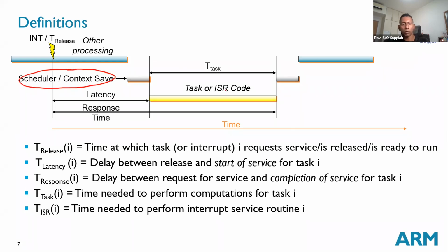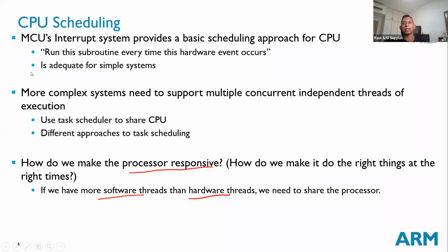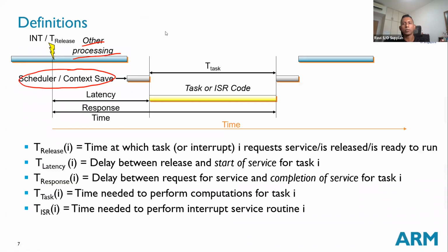If you remember from EPP2, you have learned this before, where when the interrupt is coming, you are actually busy doing something else. You are in the midst of executing some other instructions. So to service the interrupt, you need to finish what you're doing first. Correct? So that takes some time. And when you finish what you're doing, you need to save that context, the register values, the program counter, and things like that. And after all of that is done, then you are able to finally switch over to the interrupt. So that is what is happening here.